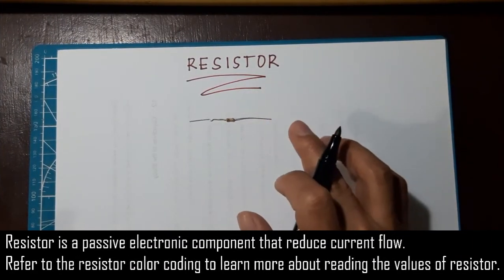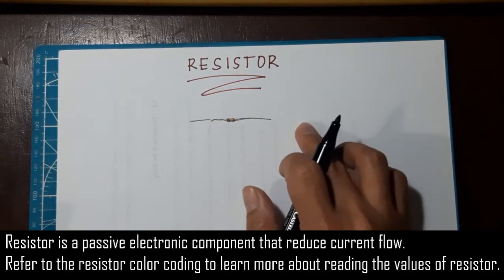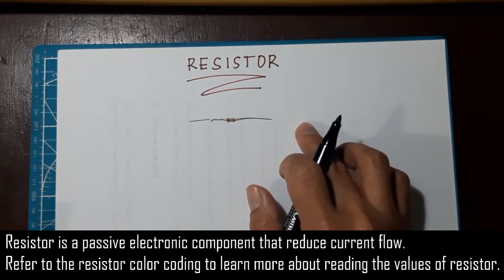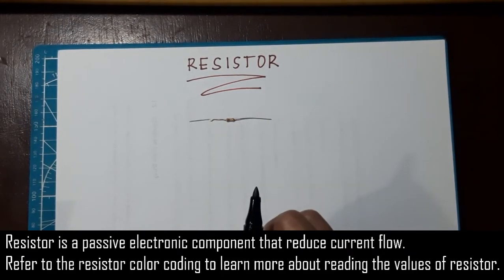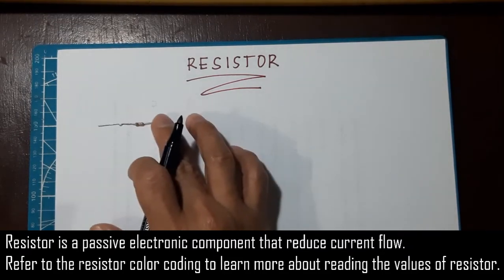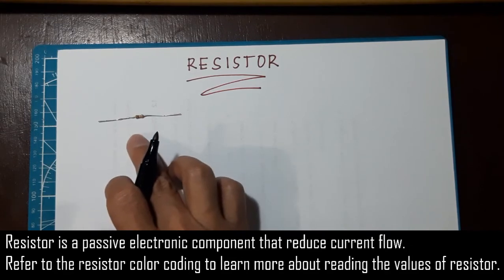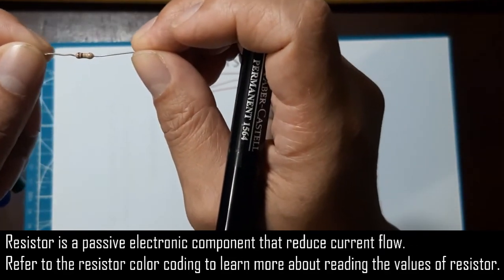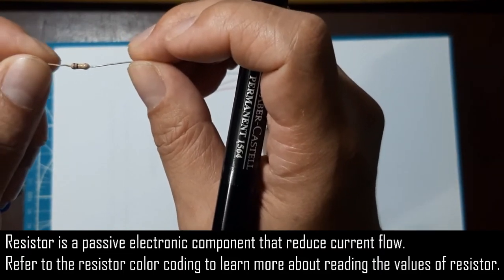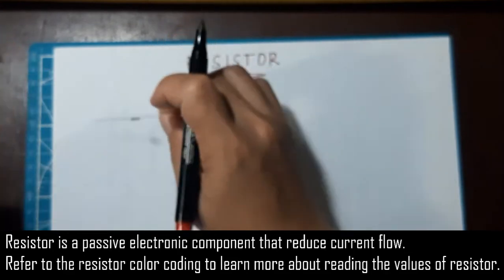Now before we test our resistor, we need to first understand the color coding table of our resistor. Basically, your resistor is color coded. This one right here, if I read it for you, has the colors brown, black, yellow, and gold.